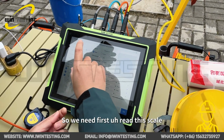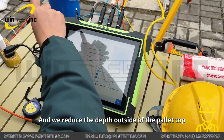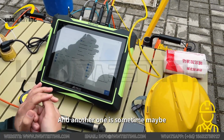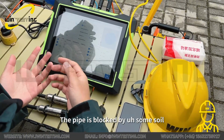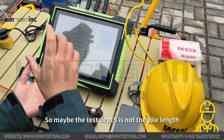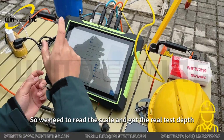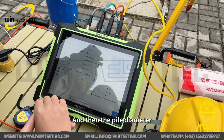So we first read this scale, and we subtract the depth outside of the pile top. That is the real test depth. Also, sometimes the pipe is blocked by soil, mud, or rock, so the test depth may not be the pile length. So we need to read the scale and get the real test depth. And then the pile diameter, only for record.